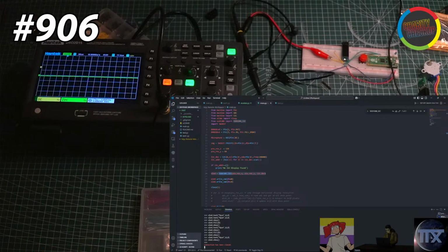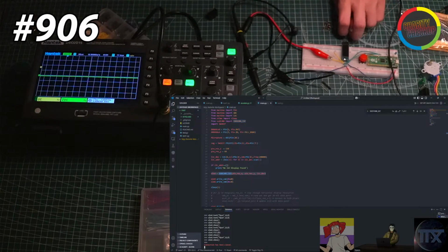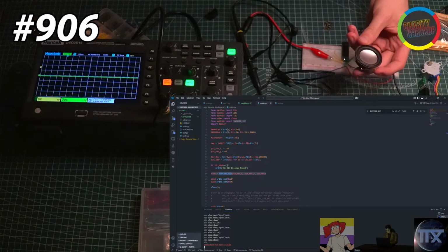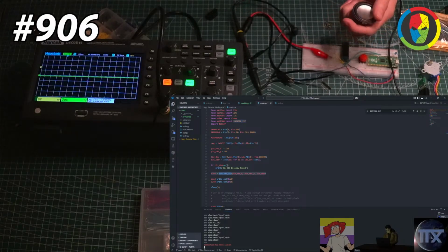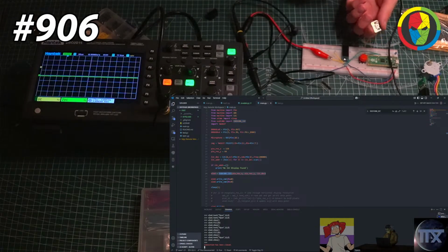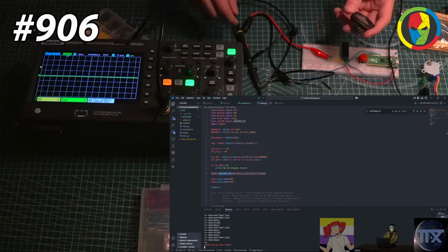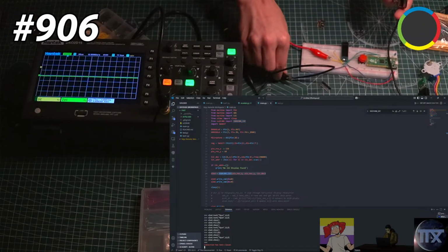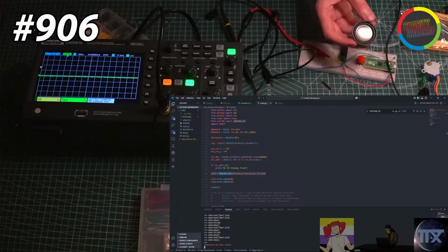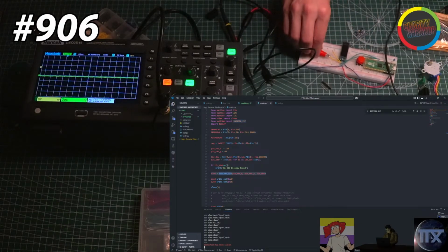Do you have a speaker anywhere? Do I ever? Absolutely. Plug the speaker directly to the oscilloscope. Speakers are also microphones, so you can literally see the waveform. I also have a microphone. But the speaker is better because that's the raw signal. That's super cool. That or a motor. If you plug a motor and spin it, you can see the output.